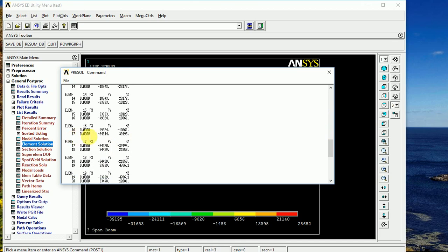There's a joint. So if I was looking on span 2 to look at the connection there, you can see I've got a shear of about 65-ish kilonewtons, and my moment is just over 39 kilonewton meters. So I'd have to design my connection on that side for span 2 to take those forces and moments.